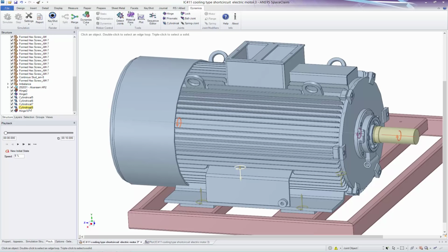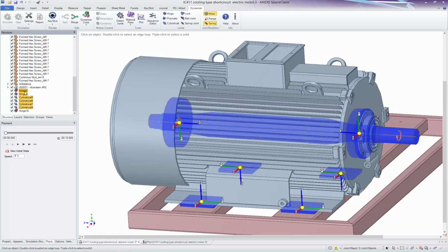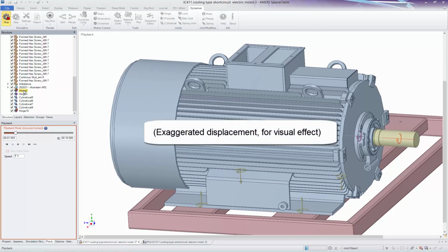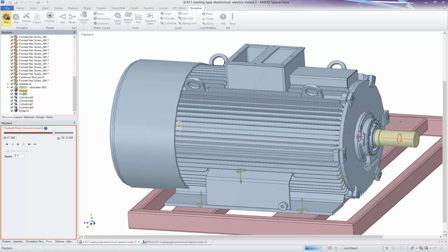Note that we have not yet allowed the system to quite settle in. It is sitting on a set of elastic dampers and is effectively floating in mid-air at the precise instant when the simulation starts. Therefore, we should give the motor a few seconds to fall into its stationary resting position before we rev it up to study its dynamic behavior.